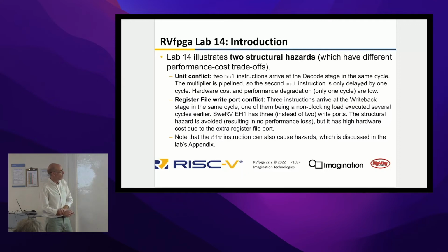Hardware cost and performance degradation are low in this case. And we also analyze a second structural hazard that takes place in the register file. And in this case, 3 instructions arrive at the write-back stage in the same cycle. Okay?